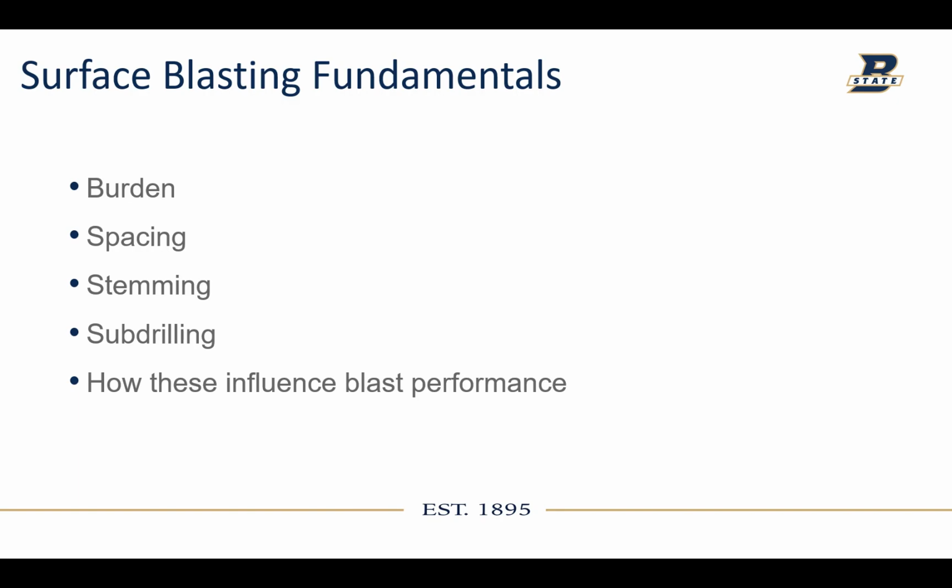So some surface blasting fundamentals, some words that you're going to hear consistently throughout this presentation. You're going to hear burden. So that's like the spacing between rows of holes. The spacing is the spacing between holes themselves. You'll hear about stemming and subdrilling, and we'll figure out how these influence blast performance.